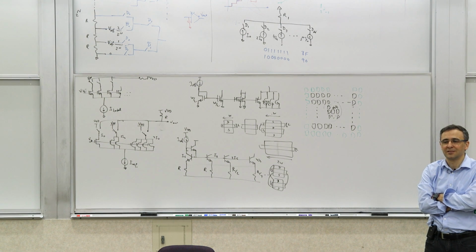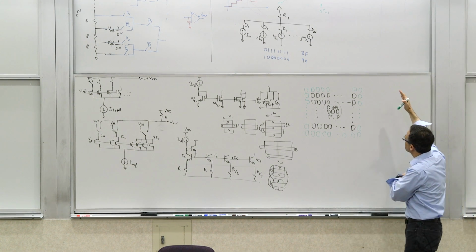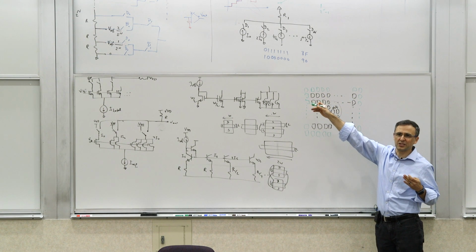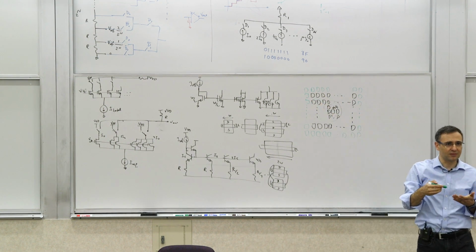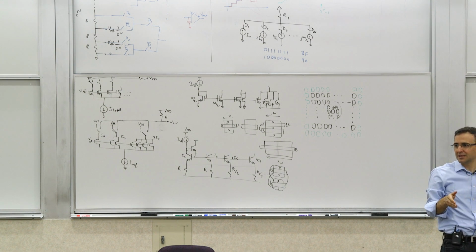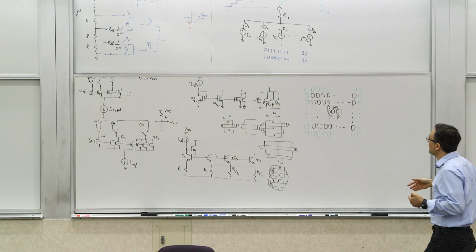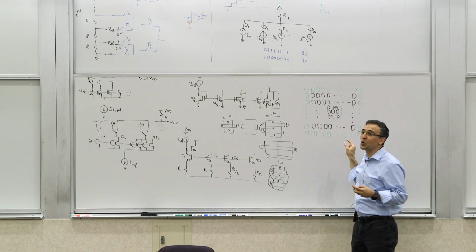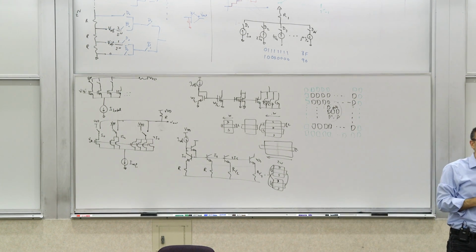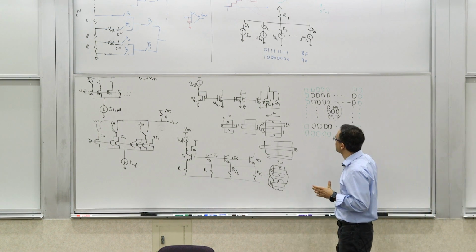Yes, Richard. Make sure the outside row experiences a similar fabrication process. Correct, because in the fabrication process, if the arrangement of things next to it is a little bit different, they may get exposed differently. They may get more implantation, less implantation, or different coverage. Etching may be different because there's more etchant available on the edge, since the adjacent ones are not being etched, so they can get over-etched. So you basically have an array. Sometimes there are 2 rows of these around it to cover it. This way you create an arrangement that is more conducive to matching.